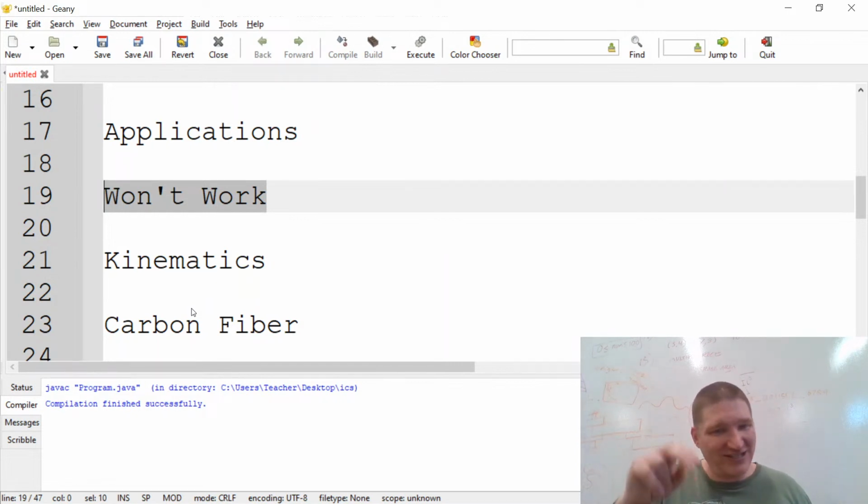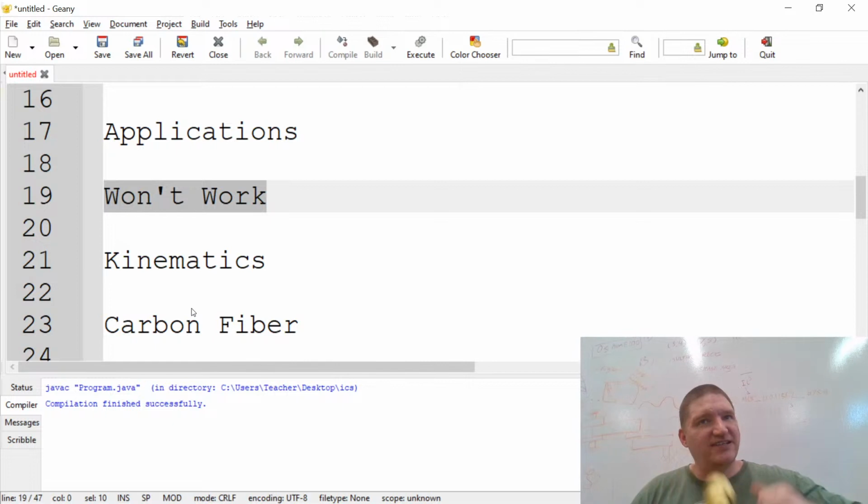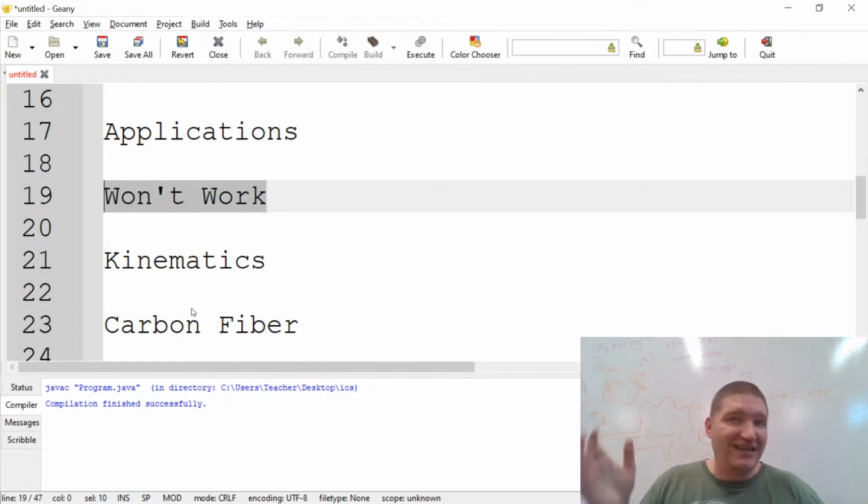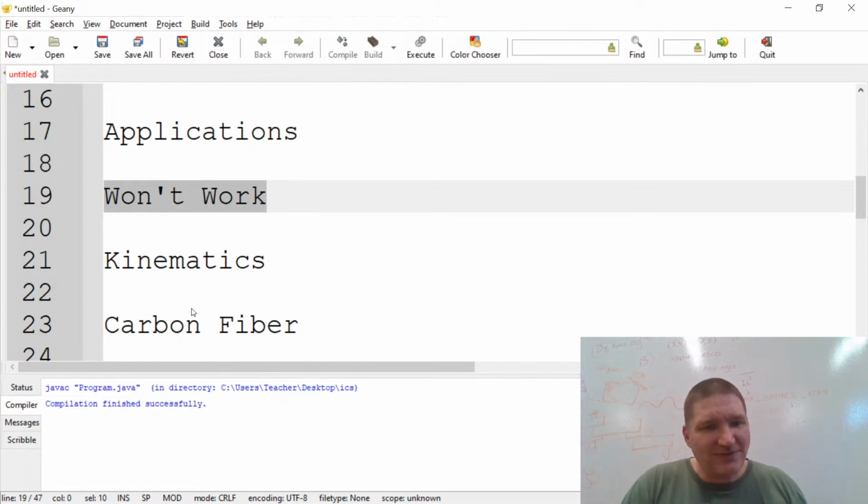If it can keep position, I can, even if it deflects quite a bit when I push down on it. But as long as it's consistent under load, I can always set the accelerations down and make this work. A lot of people put comments like, "Hey, you won't be able to do this. If you turn the corner with jerk settings, it'll cause ringing." Lots of complaints about, "Can't do this, can't do that." Like, you just set the acceleration low, set the jerk low. If it can keep a position, I can print with this thing.